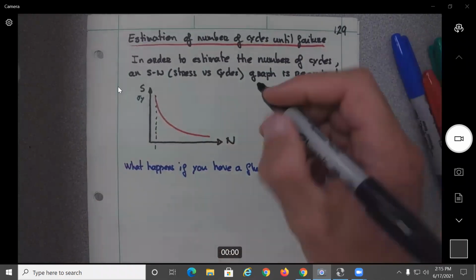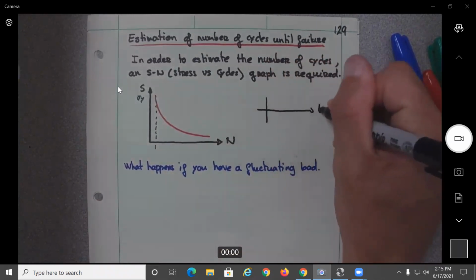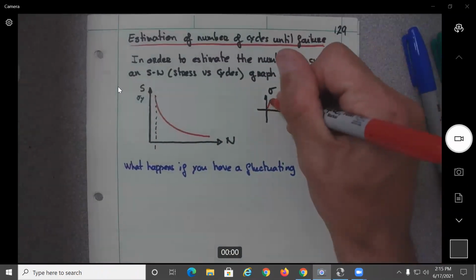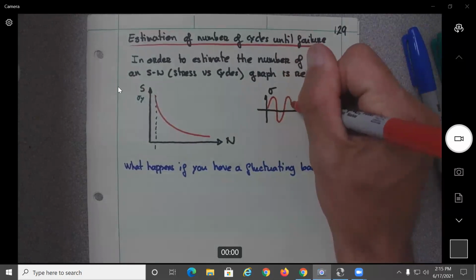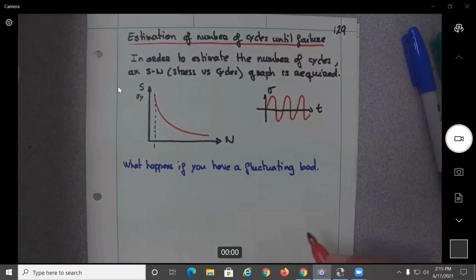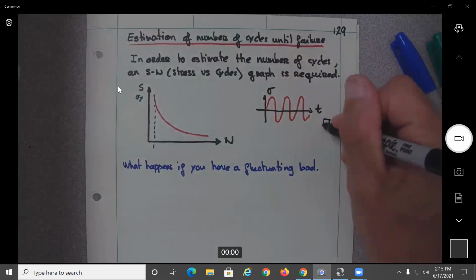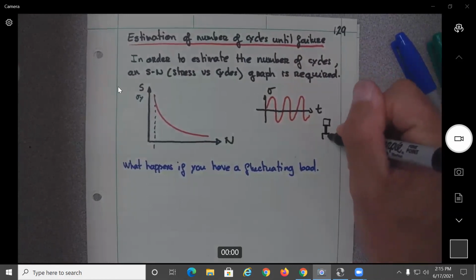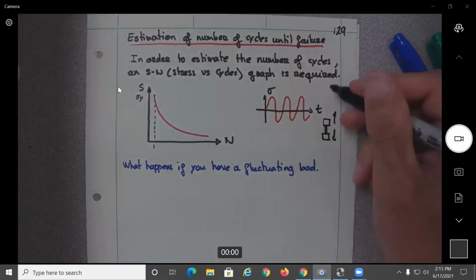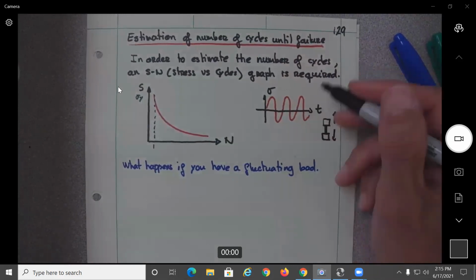Basically, these curves are created for this type of loading, which is basically fully reversed. All right, you take an ASTM machine. You have your ASTM machine. You put your component here. Okay, and you move it up and down all the time, and you can record the stresses, no? Okay, but obviously you do that for a fully reversed load.